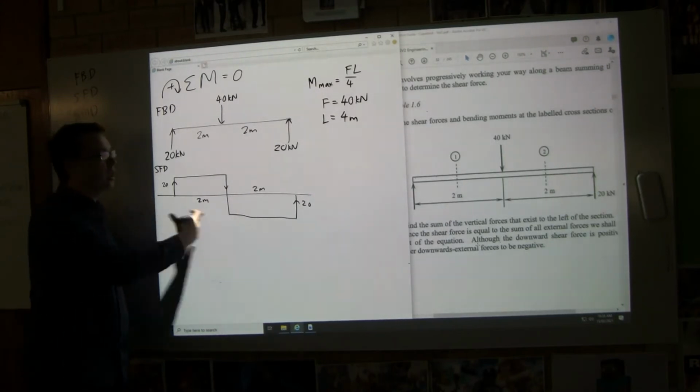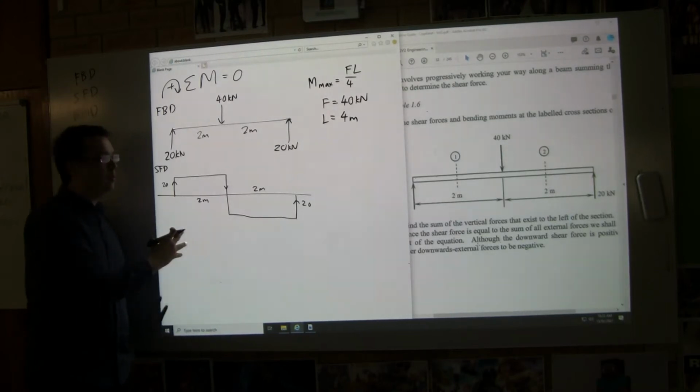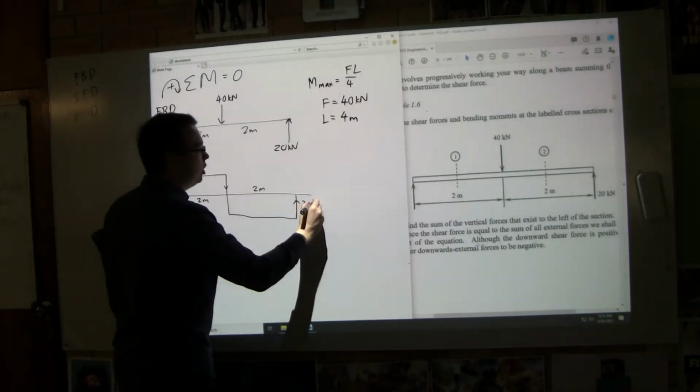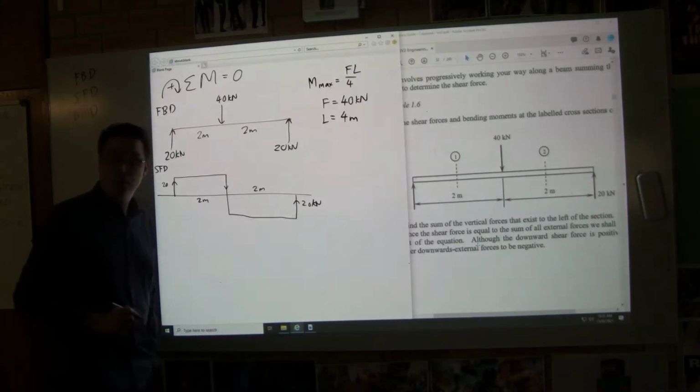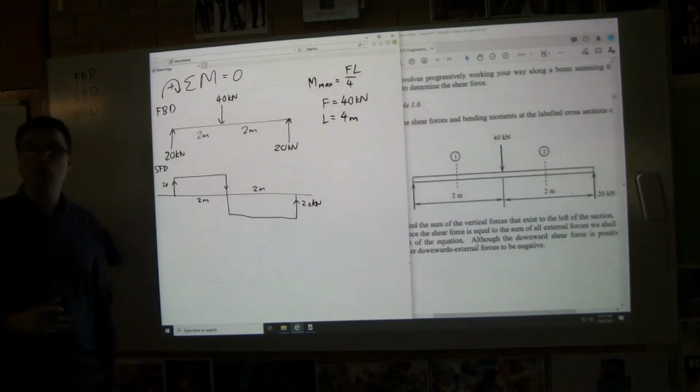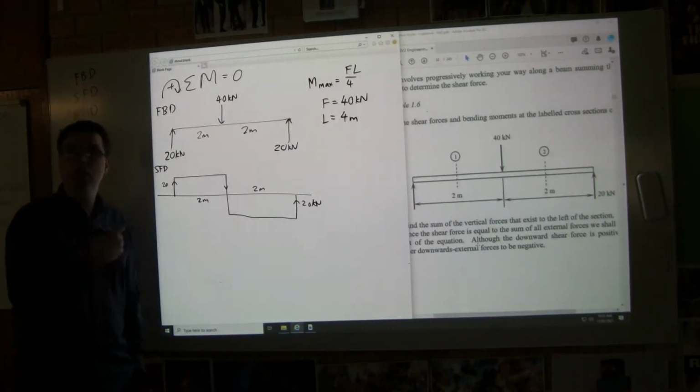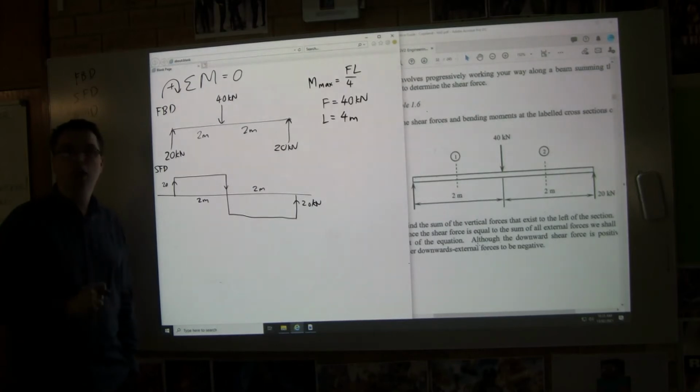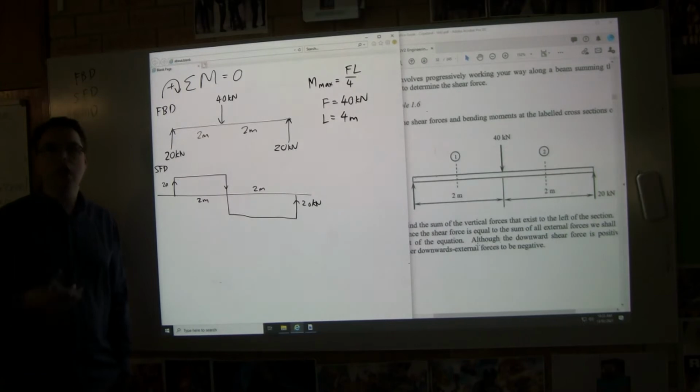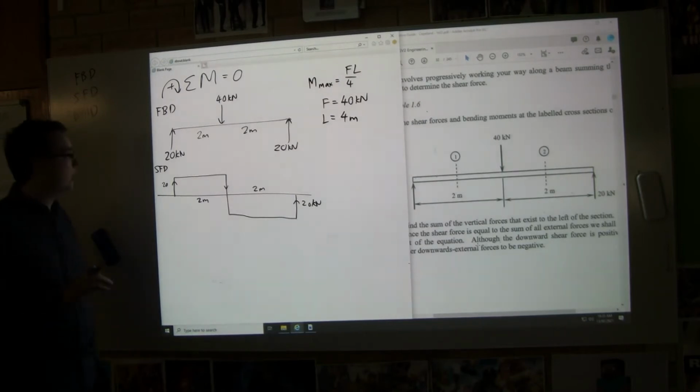As we can see in this diagram, the maximum shear force that we have in any location is 20 kilonewtons. Yeah? And that's what we're going to design for. The stirrup spacing is going to be evenly spaced based on 20 kilonewtons. Yeah? Usually we have to add some stirrups anyway. Usually stirrups are not a huge problem unless we have slabs, and we'll worry about that later.